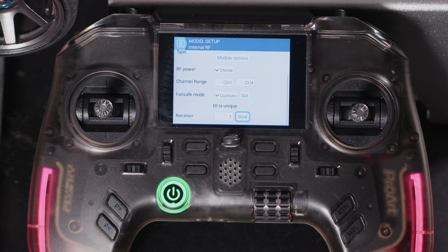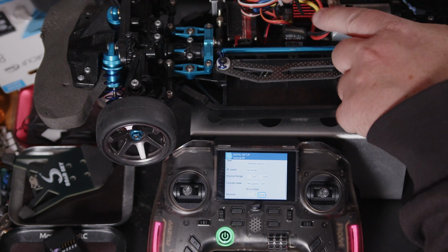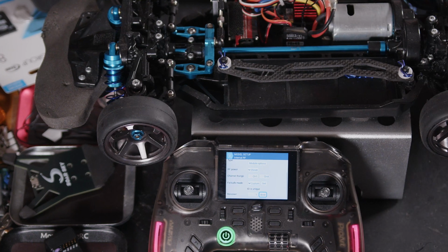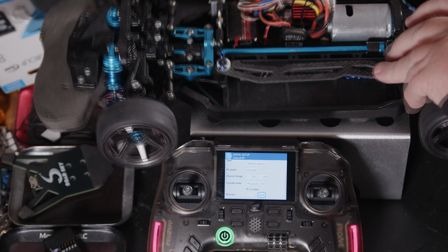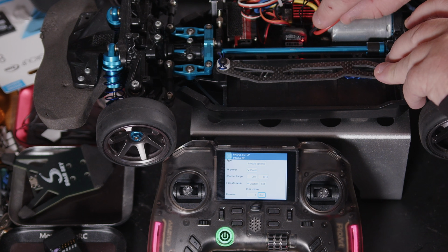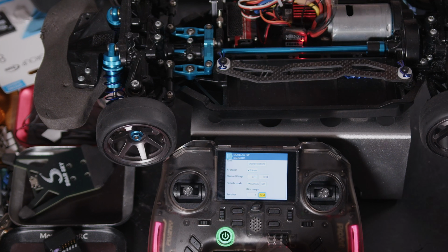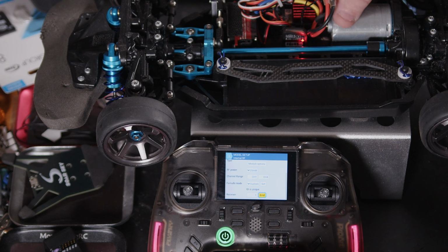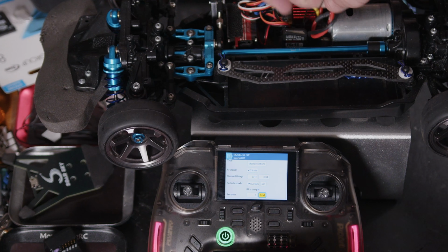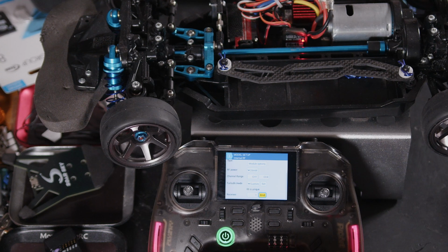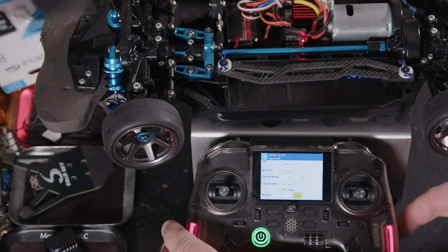So let's get a battery, and I'll get the model power on. So for this, we've got the battery connected. We're going to need the bind plug in the receiver, because this is an FGR4S. If we turn it on, so we're powered on, we've got it in bind. If we tell the transmitter to bind, so we're now bound up as the lights are on solid. Should be able to power it off. Remove this bind plug, power back on, and then we should be bound.